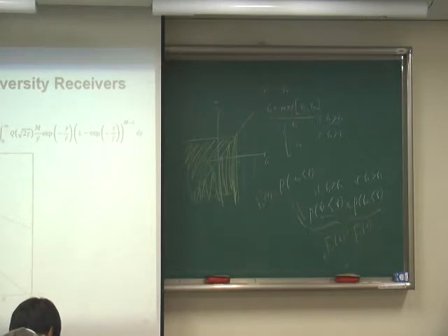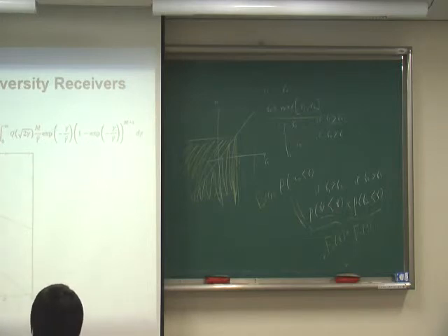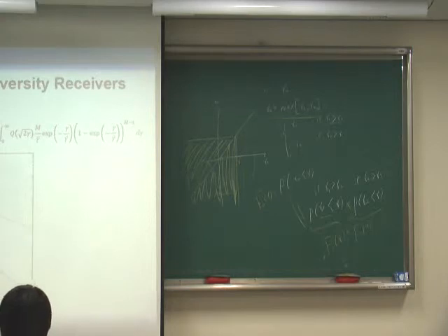And for selection combining, we also plot the BER with different M values. You see these BER pictures. Here again, as you see, if you increase the number of antennas, you see a different slope, meaning a different diversity order. So this is what we plot.